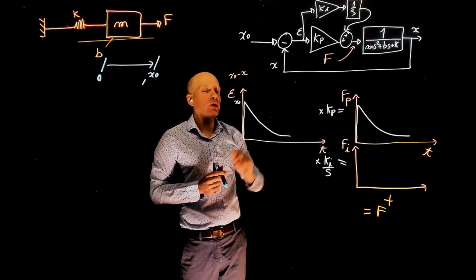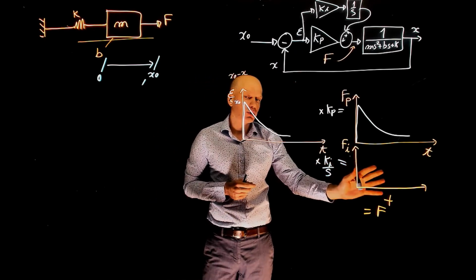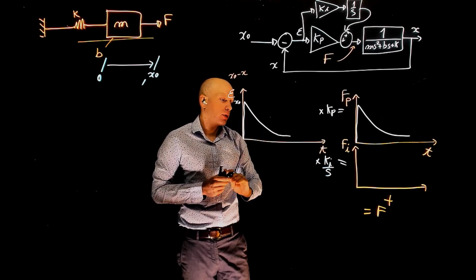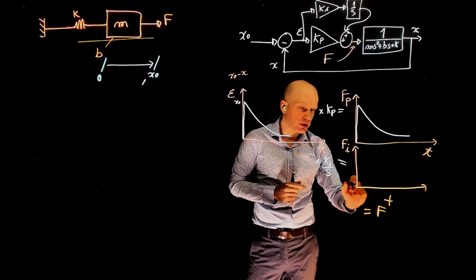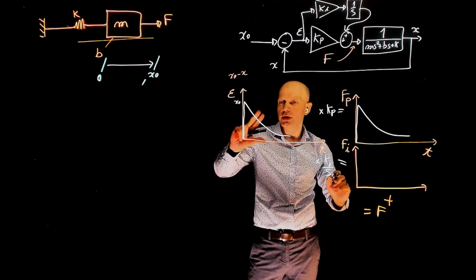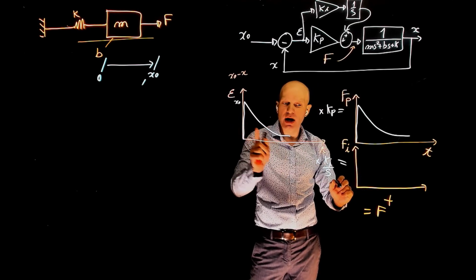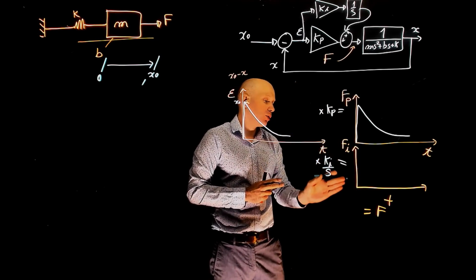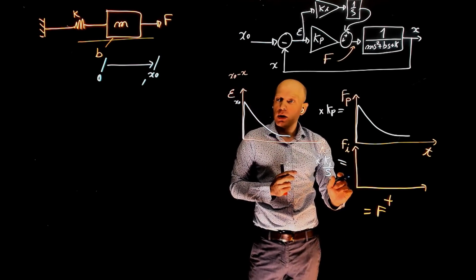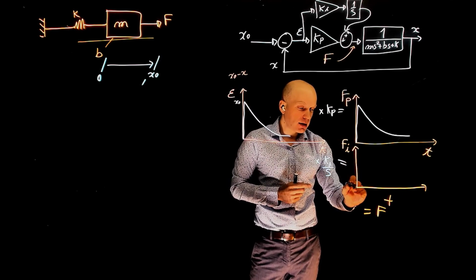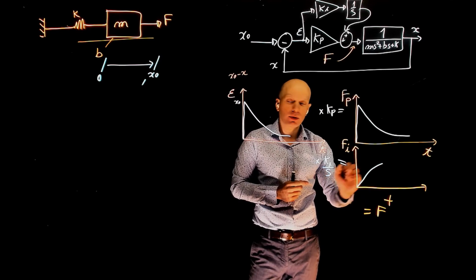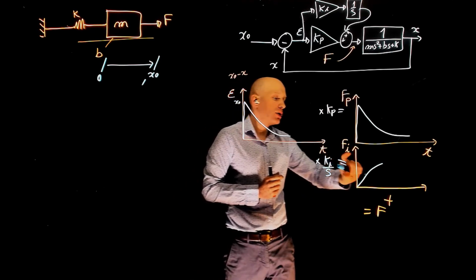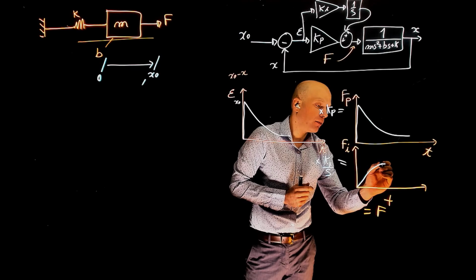Very well, now that we have the integral controller, what is happening? The integral controller is looking at the integral of this error, which is the area under it. So the integral controller at the beginning will start to rise sharply because the area here is large. Of course, the area times Ki. So by controlling the integral part, you can control how fast this integral will build up. So assuming a reasonable value of Ki, this would now start to integrate like that. So it's going to go fast at the beginning, and now the error is decreasing, the integral is getting slower.